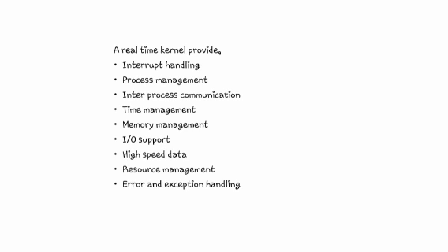A real-time kernel has some specifications. A real-time kernel must provide interrupt handling, process management, inter-process communication, as well as synchronization, time management, memory management, I/O support with the help of drivers, high-speed data, resource management, error and exception handling.